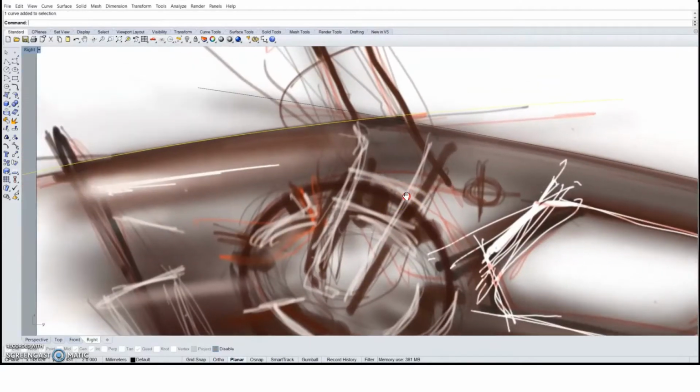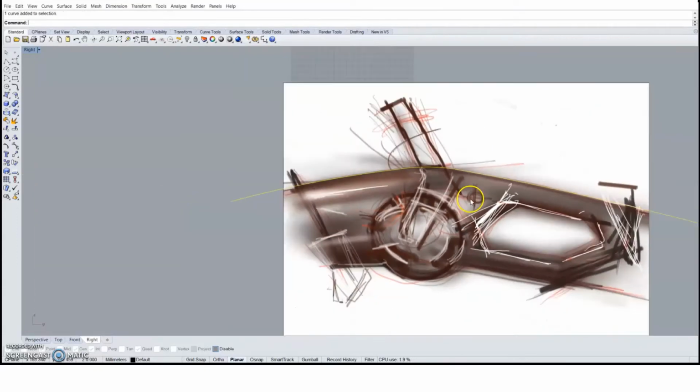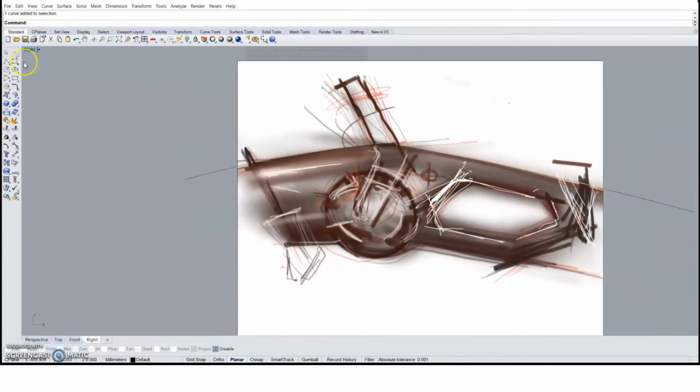3D model. So what we are doing here is using simple curves, and then we create fillets, basically radiuses, that join these two curves to make it into a more complex curve, which will become the rail in another feature that we use to create the surfaces. So you see now the two simple curves have become a much more complex curve.